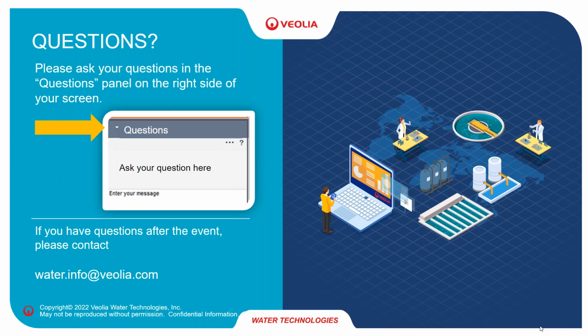The objective of that media is to provide biofilm surface. The K5 offers quite a lot of surface with a specific protected area of 800 square meters per cubic meter. And at the same time, we want a media that is somehow porous, which has openings allowing water to flow through the media.